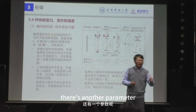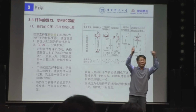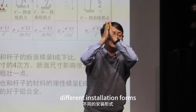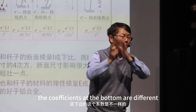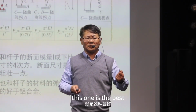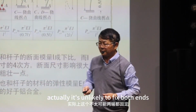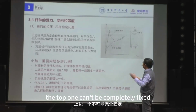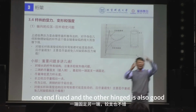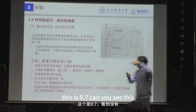There's another parameter which might be quite useful for your installation and is very instructive. Can you see this? These are different installation forms. The coefficients at the bottom are different. Which form is the best? It's this one. Both ends are fixed. Actually, it's unlikely to fix both ends. The top one can't be completely fixed. The bottom one I can fix completely. But now this one, one end fixed and the other hinged, is also good. This is 0.7. Can you see this?